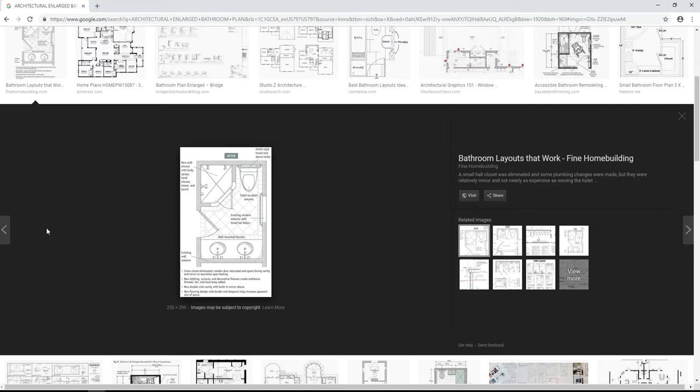Bathrooms are the same. It's not a life safety issue, but it's an accessibility issue. So you need to make sure that there is wheelchair clearance, that the toilets and urinals are at the correct height for accessibility, that the sinks have clearance so a wheelchair can maneuver in, or a person who has a challenge with regards to accessibility can reach them. Or the door opens appropriately so people can enter and exit the restroom, right?